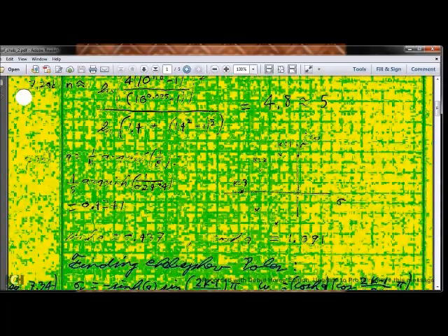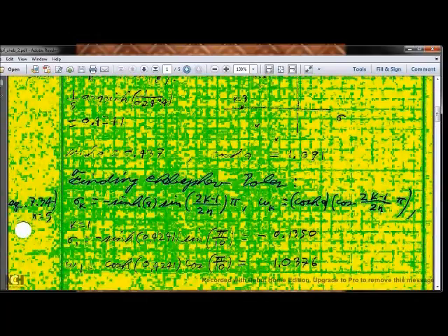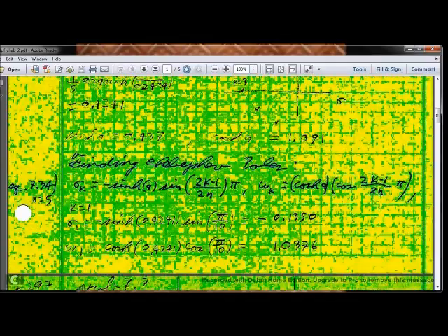Here's a parameter A, and I'm sorry this didn't show up very well. It's 1 over n arcsine hyperbolic, 1 over epsilon. We calculate that as a constant. Here on the right is a sketch that didn't show up very well, but it shows the pole locations. They're on the left half plane. Here's a sigma axis, or the real axis, and the imaginary j omega axis. Sin A, hyperbolic sine of A, and cos A calculated.